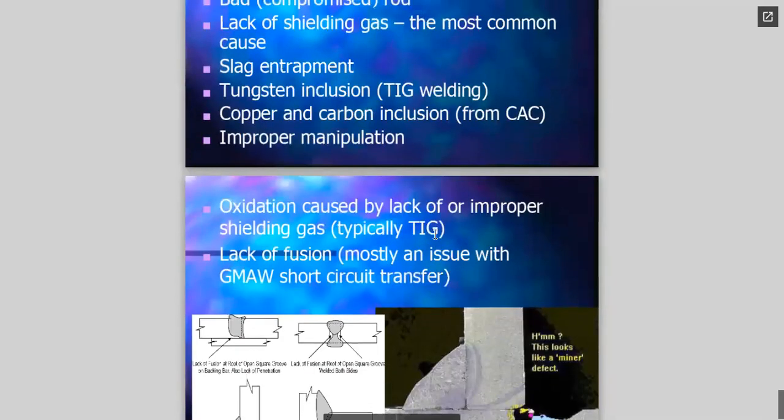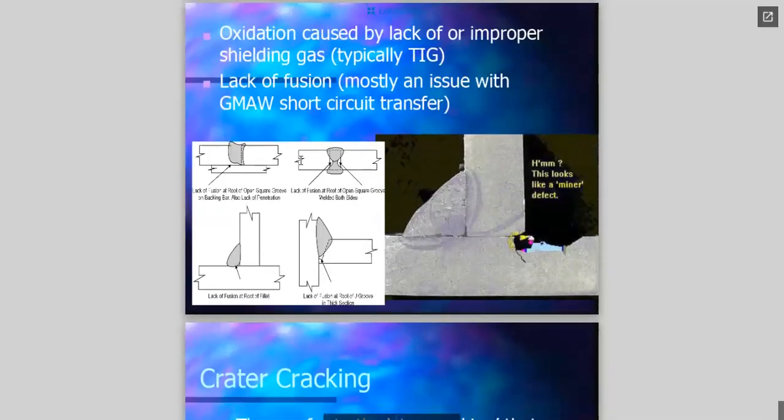This is all defects. So what we can have here is incomplete fusion. What this slide is showing is that we are not getting down to the complete bottom of this weld, and there's a hole in the bottom. That's not what we want. Here, we got a couple gaps on the side where we didn't get in all the way. Right here, tucked right in that corner, there's not any fusion there. And right down here, we never got the bottom of this. A couple ways of fixing this: you open up the angle a little better so you can reach down to the bottom, or you come back from the bottom, grind a bunch of this out, and weld it from the bottom, welding it from both sides, if you have the ability to do so.